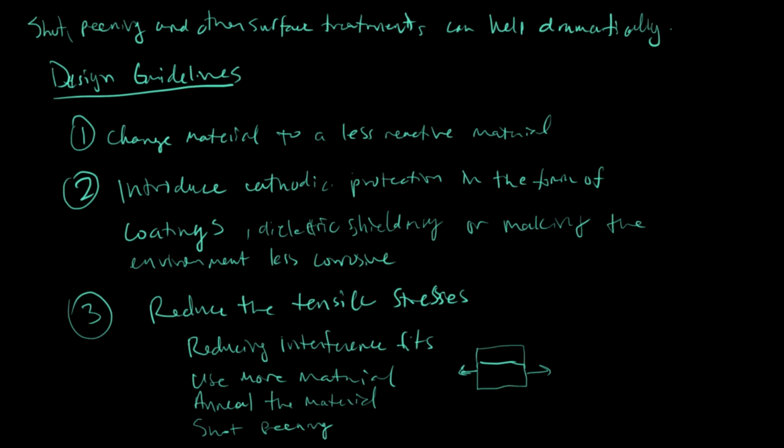The only caveat is when you anneal a material, you are making it less hard and more ductile, and we know that the resistance to fatigue is improved by having harder materials. So there's likely a trade-off there that you need to be aware of.